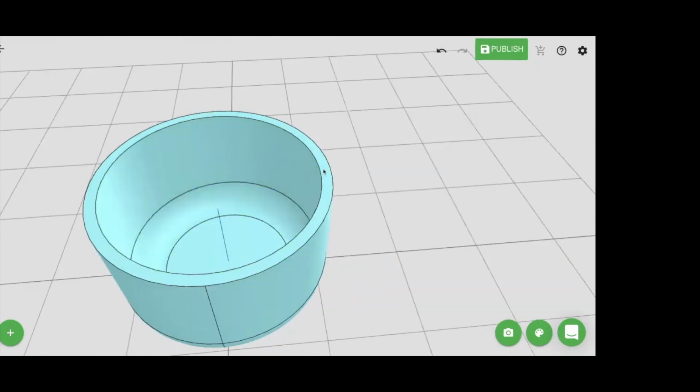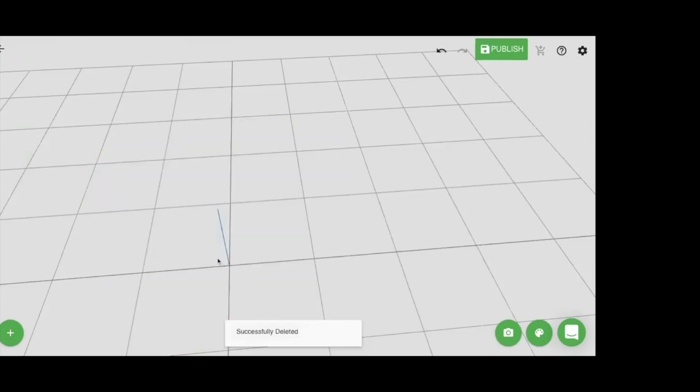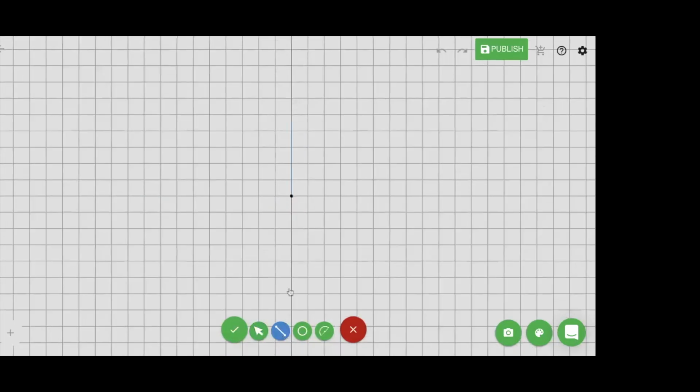But if I wanted to make the same kind of shape, or something similar, I could also approach it again, there are multiple ways. It's like Bob Ross. There's no mistakes, just happy accidents. I could go back here, draw a single vertical line, select it, and again with that construction, because this is going to be the pole that I use to revolve this L shape around. So it's not going to be actually used in a 3D model, just used to create the 3D model.